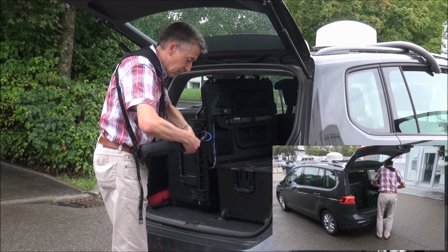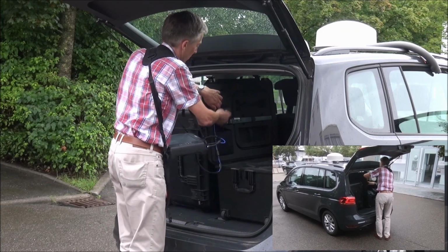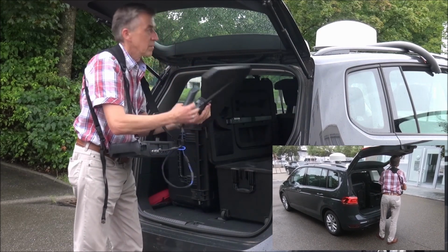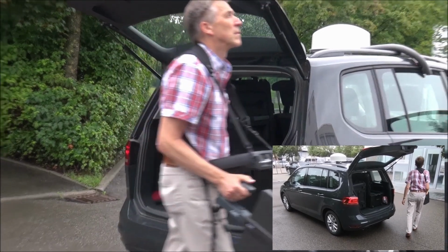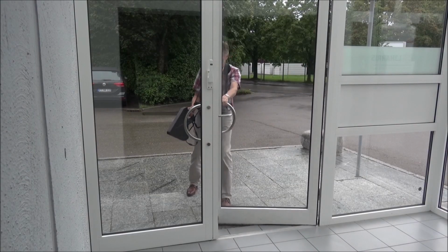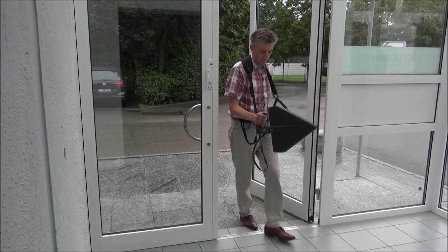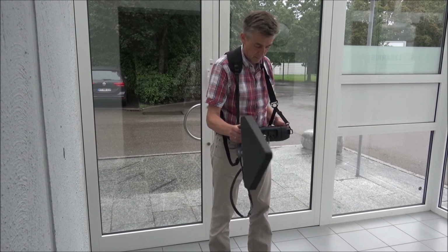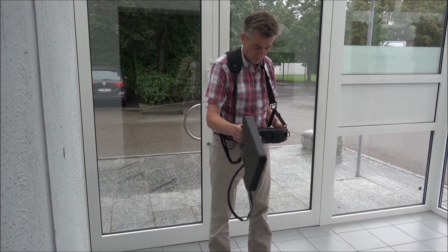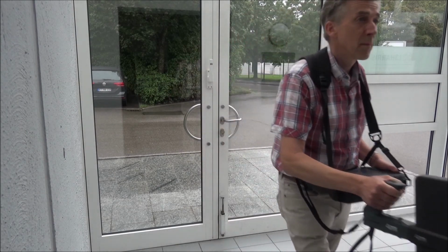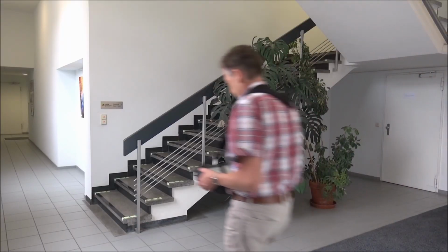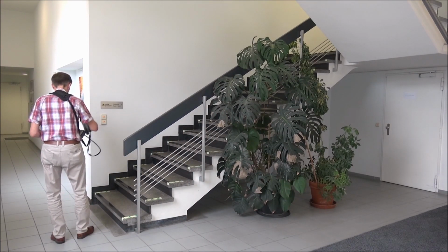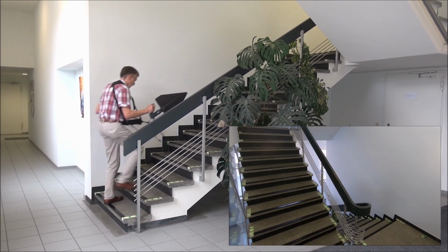It is hence recommendable to first target SignalShark's localization result before following up on other traces. Bear in mind that SignalShark's localization result is based on hundreds or thousands of bearings from different spots. Also note, if the interference source is located on higher levels of a building, signal strength will most likely drop when approaching that building on foot due to shadowing effects. Hence, when targeting SignalShark's localization result on foot, sweep your directional antenna not just over azimuth, but over elevation too.